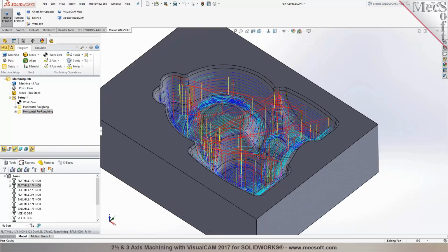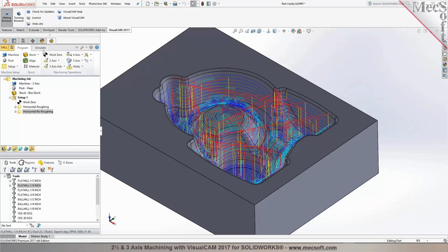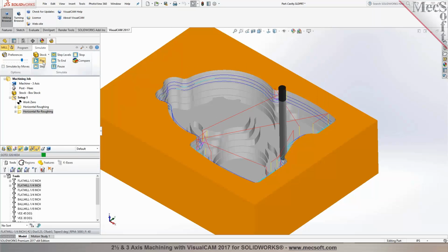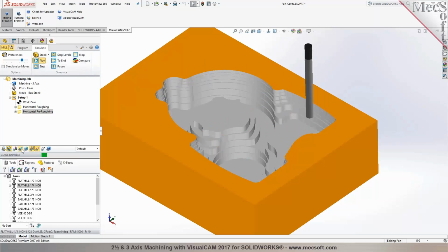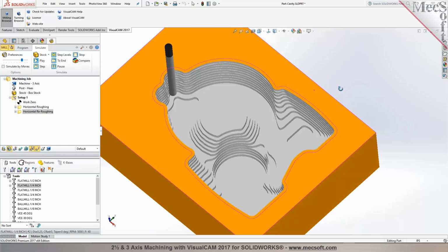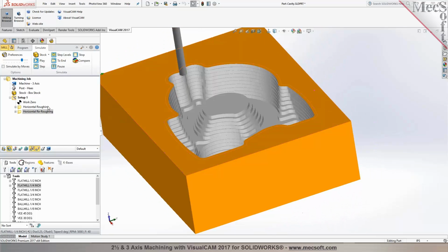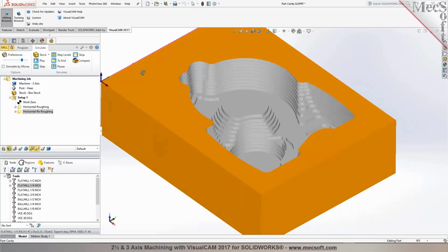And since I changed it from 25,000 to 15,000, you'll notice that it's only cutting areas where material is being left from the previous operation. So this is re-roughing, which is offered in a Pro and Premium configuration. So the Pro would be ideal for your application needs. You go from roughing down to a re-roughing operation.